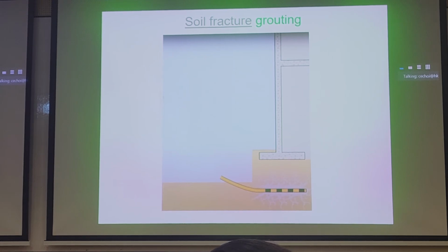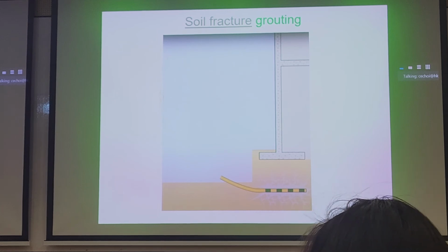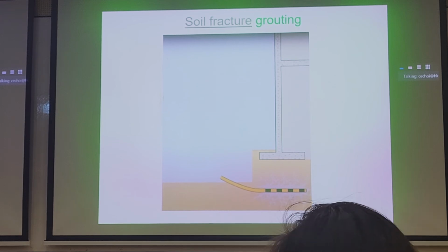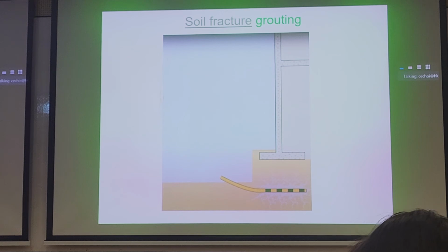Now, not so easy to do in practice. You have to be very familiar with how to form fractures in the ground. Of course, there are theoretical considerations, but I think that's well beyond the scope of this class. And in fact, for all types of grouting we talked about, fracture grouting, jet grouting, displacement, compaction grouting, there are actually analytical equations, but this is well beyond the scope of the class. However, for example, if you're talking about permeation grouting, why do we talk about rheology? Because you need to use some concepts from rheology: what's the shear rate, what's the viscosity, so we know how far it permeates.